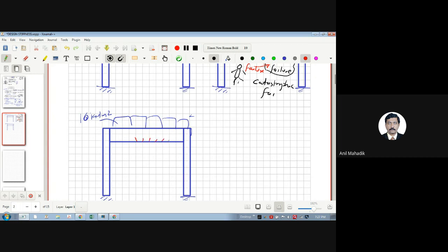So we have seen cracks in the structure, and when you see the cracks, then definitely you get an idea that there is something wrong. If there is a crack, it means there is some overloading or danger to this structure, and then you can evacuate easily, right? Evacuation is very possible, and then you can repair the structure, do the structural audit and so on. So it is giving me enough warning before actual failure.